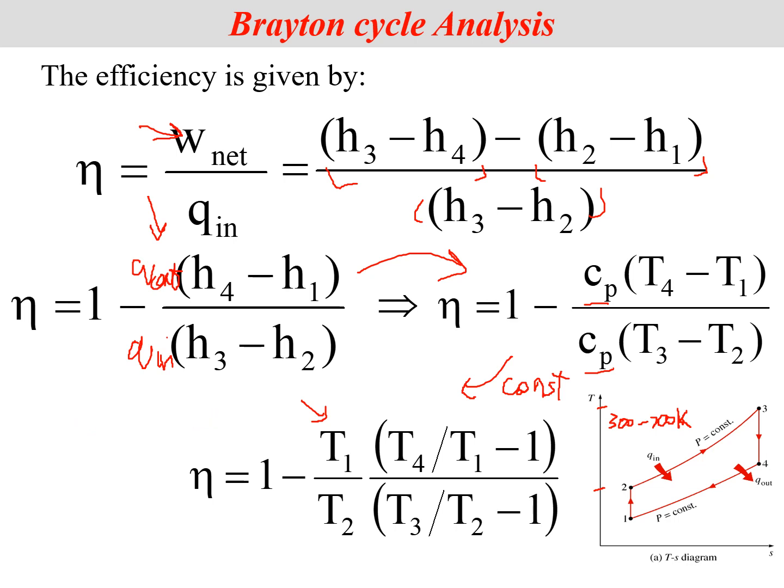Okay, so if you have the direct enthalpy figures, that's the best. And if not, you can just take the instantaneous CP value. And even if you don't have that, you can just take the temperature ratios and solve this. But this is the least accurate. Then this is more, and this is the most accurate figure.